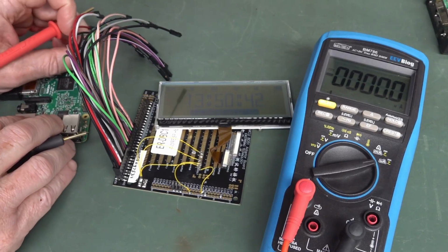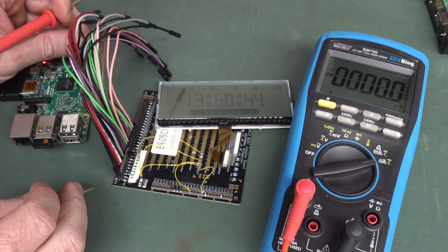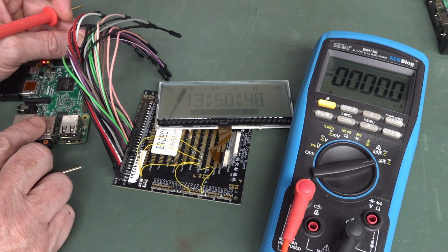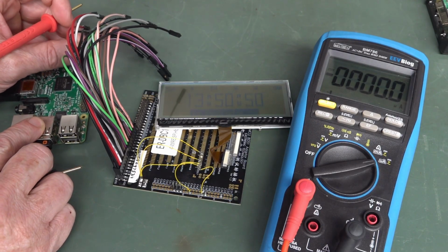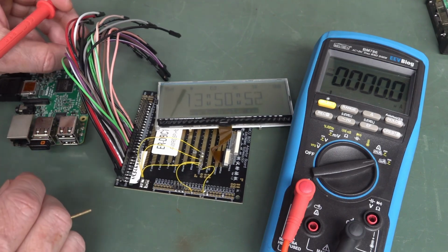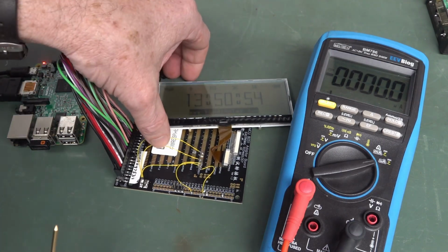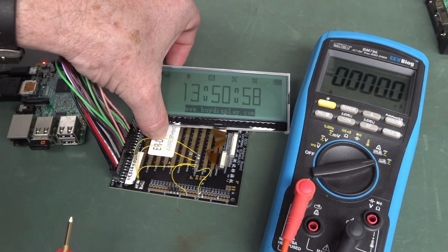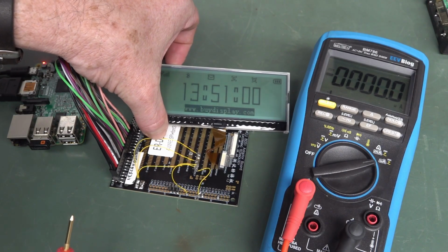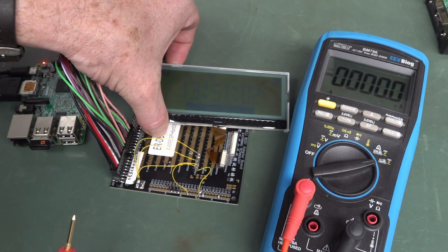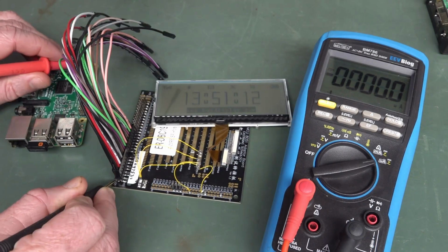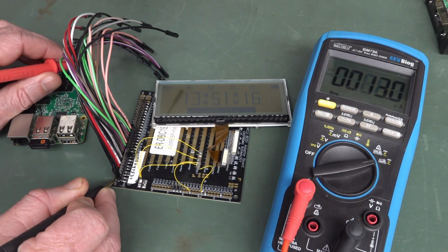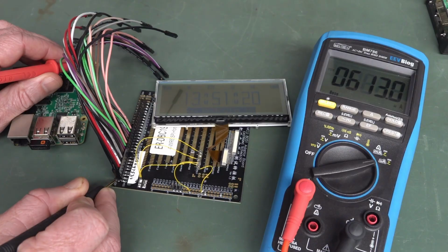Alright, so let's measure the current consumption. Oh, there you go. I disconnected the power pin and the contrast has changed because it's being powered by effectively a different voltage, a lower voltage, because it's going through the pins. It's going through the I/O. Whoa, there we go. It's jumping all over the place. Anyway, let's power that. And, oh, 600 microamps. Well, so much for that.